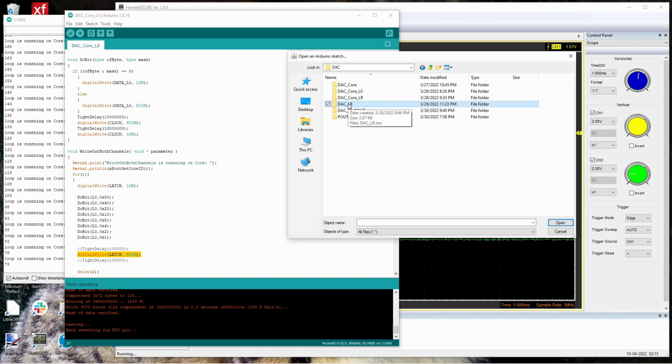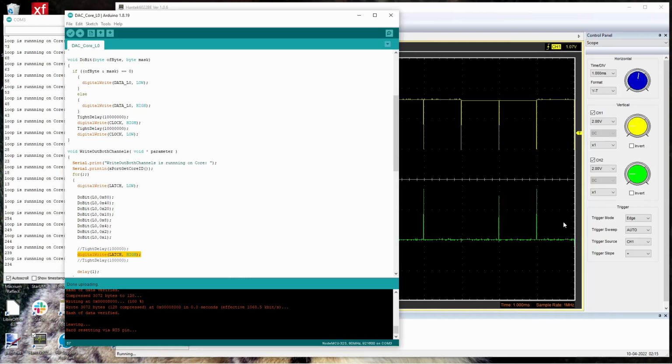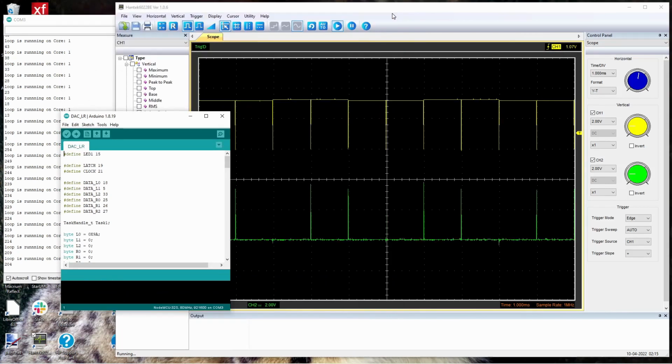But it's promising enough to move on to the next experiment. So we're going to hook up all 6 of them now. And when I say all 6, let me explain how I've got it wired up. I'm not using that ganging idea where one shift register shifts onto the next. I have enough pins on this. This ESP32 is totally committed to this application. So I have enough GPIOs to have 6 bits of data that I can put out onto the shift registers in parallel.